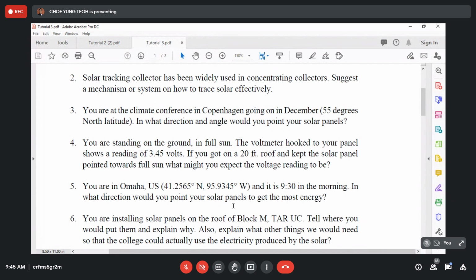So you cannot say that when the photo sensor receives whichever amount of sunlight, that is the direction. No. So normally they'll use a few photo sensors. If you put them at different locations, then they rotate until all of them get the maximum value. That is referred to as the direction of the sun.